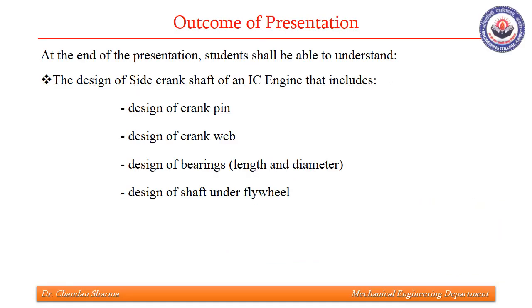So at the end of this presentation, students shall be able to understand the design of side crankshaft of an IC engine, which includes design of crank pin, design of crank web, design of bearings, basically their length and diameter, and design of shaft under flywheel.